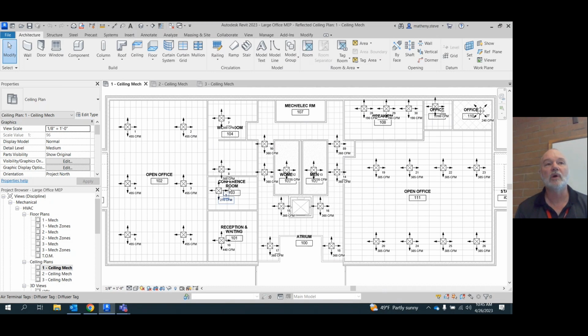They're called variable air volume fans, VAV units. Each of your secondary systems is going to get a fan to help boost that airflow that's coming down from the roof, through the plenum, out through the primary duct, and then it's going to get a shot of fan that's going to boost it the rest of the way. Okay.